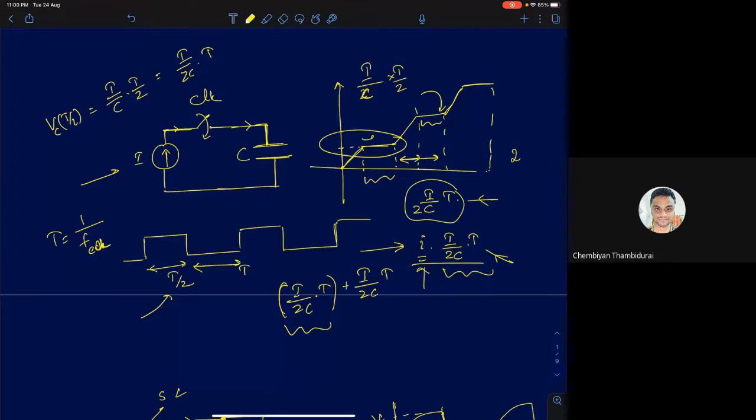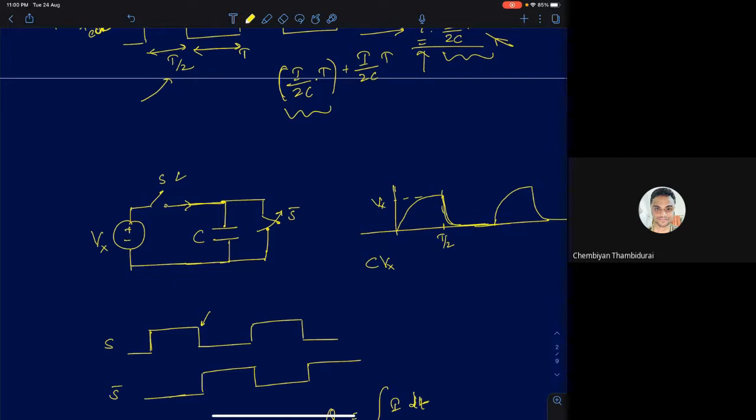So if I can somehow eliminate that accumulating ability, then I can try to mimic the behavior of a resistor. So that's what I've shown here. Instead of a voltage source, I'm showing it using a current source. I have two switches shown here. One switch is controlled by a clock signal. The other switch is controlled by clock bar, the inversion of the clock signal.